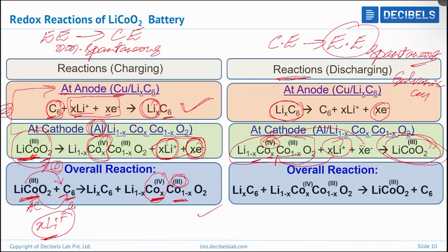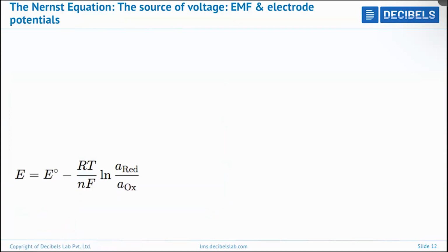The lithium ion has to come out from the cathode, that too from a solid matrix, so the resistance experienced by the lithium when coming out from the solid matrix is different. Then once it enters the electrolyte, that resistance is different. Then it has to pass through the separator, then it enters the graphite. So it has to experience various resistances. As a result, the voltage drops, and we call it overpotential. I'll be touching on those concepts in my future slides.